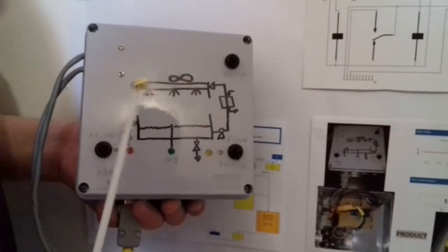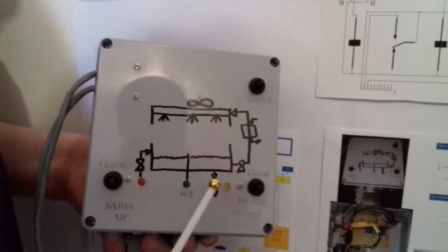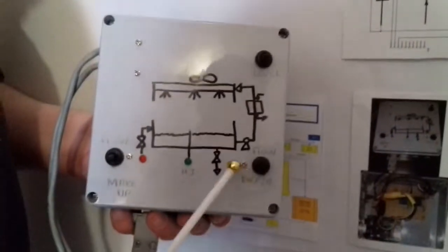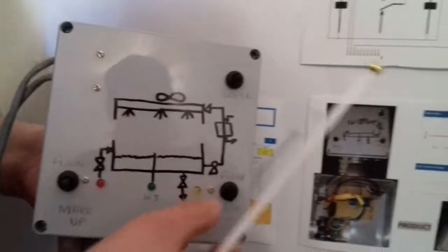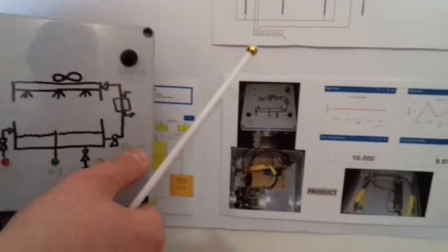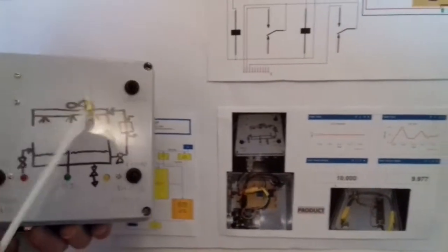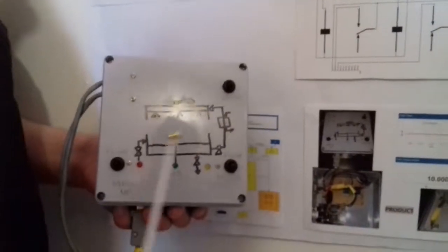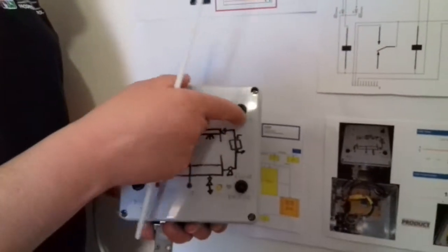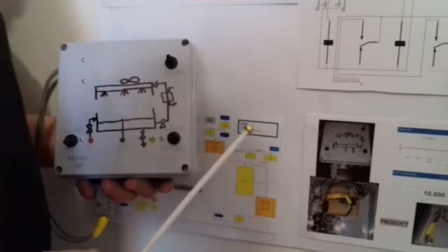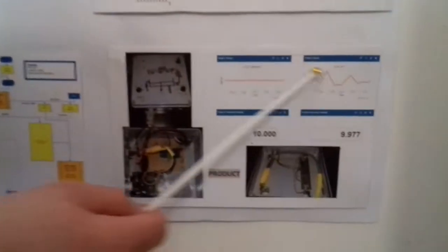As that hits the set point, the valves will close and the totalizing will stop. If it continues past the set point, the drain valve will switch open, the light will switch on, and the drain will start to totalize. At the end, the drain will switch off, the LED will switch off, the totalizing will stop, and at some point the makeup might start again because it's not on set point. As it makes up, the level will come on, this will switch off, and the level will switch off. So this whole process, or the IP, sits within the algorithm to control this level.